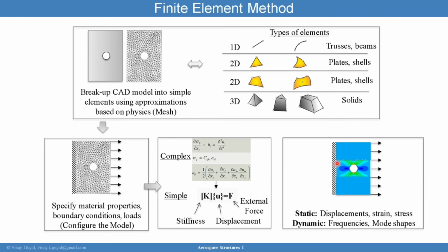What is interesting about finite elements is that not only can you visualize the stresses and strains over the body of the material, which could vary across the body, but you can also visualize how the structure deformed and deflected, which is very, very useful to understand whether the modeling is correct or not.